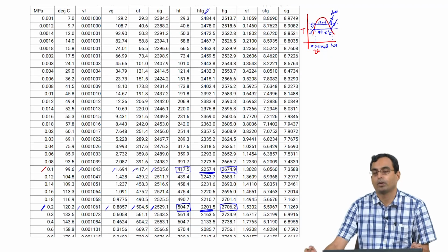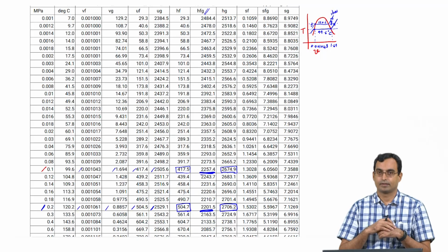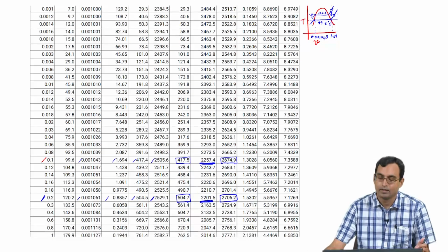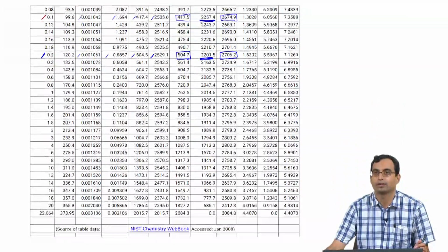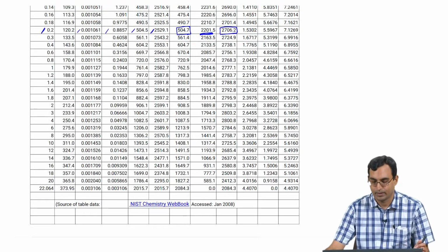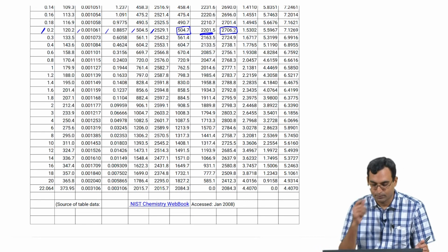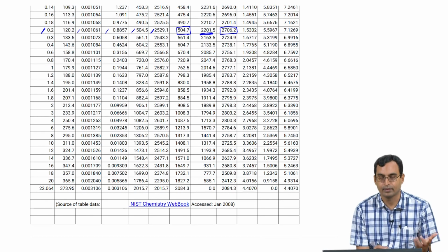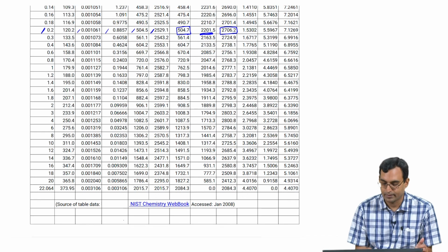The question is, what do we think would be the last pressure on this? So, we have already discussed that in some sense. The last value on this must be the value at which you can no longer have any difference between the liquid and the vapor, and we know that that point is what we call the critical point. So, the last value here is for the critical point where the pressure is 22.064 megapascal, so essentially 220 bar. The temperature is 373 degrees centigrade.